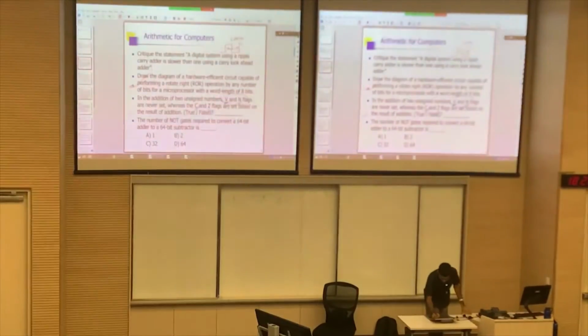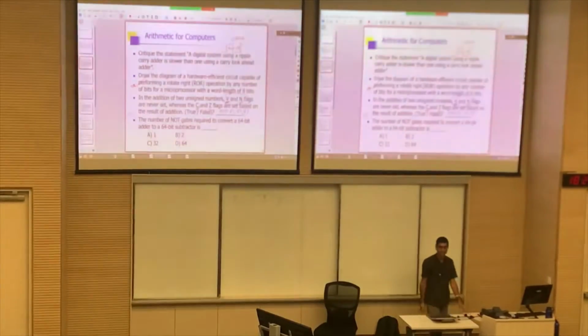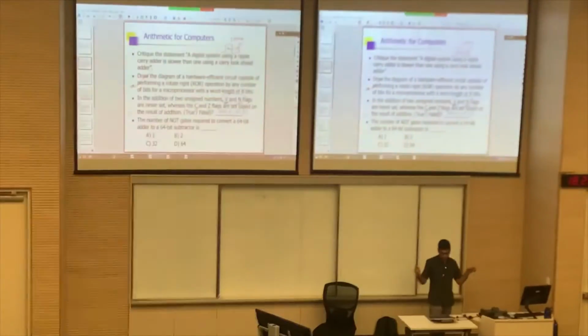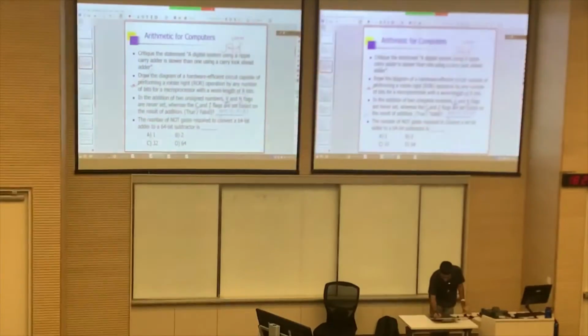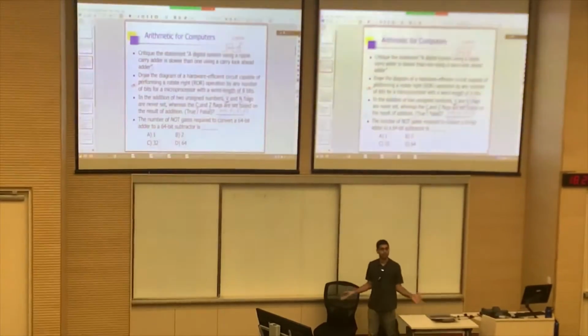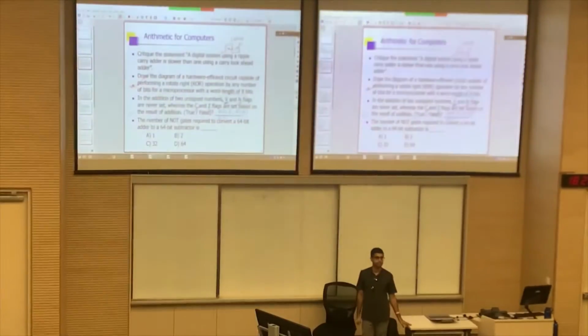So for example, if you use, let's say, R1, R2, R3, where you know R2 and R3 contain unsigned numbers, and the next line you are using is VGT, you are doing it horribly wrong. Why? Because GT is a condition that is to be used for signed numbers, not for unsigned numbers.